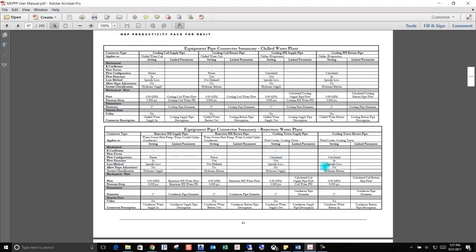So then on the piping side, really flow propagation boils down to plants. Someone's making a resource and someone's using it. And that's how we've set up these pages. This is meant to be the consumer. So for chilled water, the chilled water plant, for example, these are the connector settings for the consumers, for all the coils of the chilled water. And then the chiller that's making the chilled water, here are those settings. So once again, these are set up for flow propagation, pressure drop calculations, all of that.